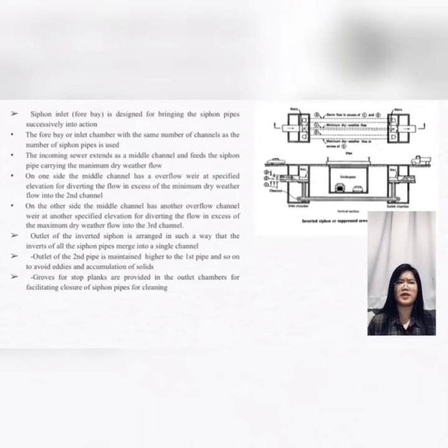The outlet of the inverted siphon is arranged in such a way that the inverts of all the siphon pipes merge into a single channel. The outlet of the second pipe is maintained higher than the first pipe and so on, to avoid eddies and accumulation of solids. Grooves for stop planks are provided in the outlet chamber for facilitating closure of siphon pipes for cleaning.